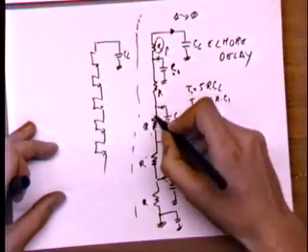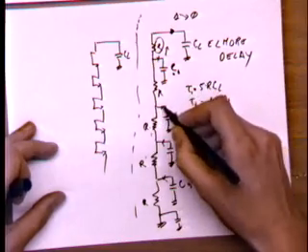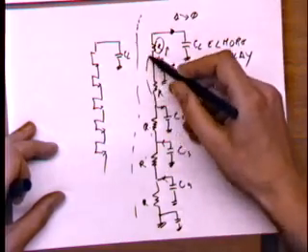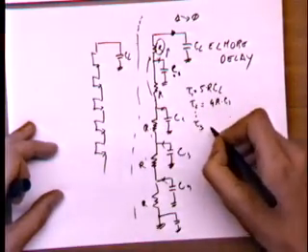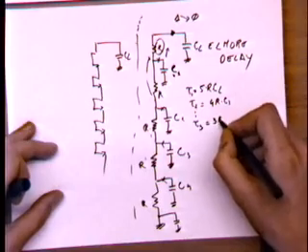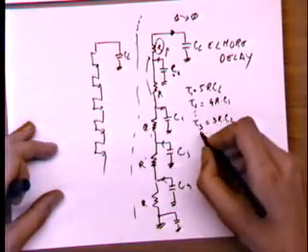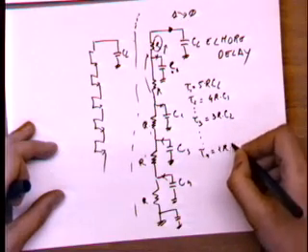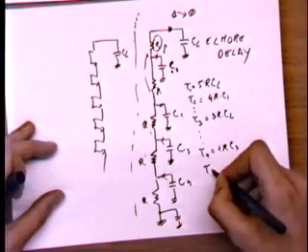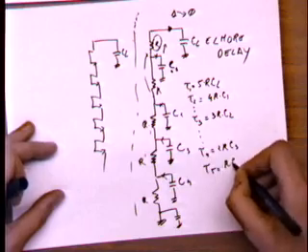And then you will do the same for tau 3, for this other capacitor. Again, looking upwards, you see open, so it doesn't matter. Looking down, you see 3R. So we can call tau 3 equal to 3R C2. And so on. Tau 4 is going to be 2R C3. And tau 5 is going to be R C4.